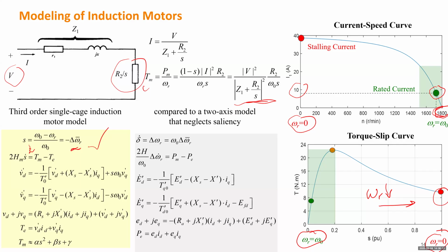So you see this one and that one are basically very similar. Okay, and this one is very similar to that one. But definitely for the synchronous generator you have field voltage, but for the motor you don't have field voltage. The field voltage is really caused by the slip, because the difference of speed will induce the voltage. Okay, so this one tells where this field voltage comes from.